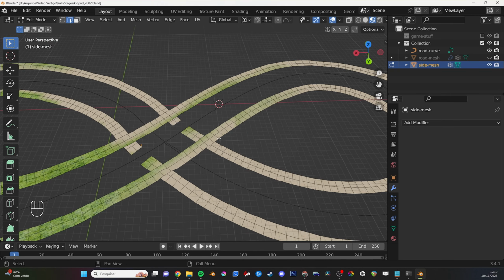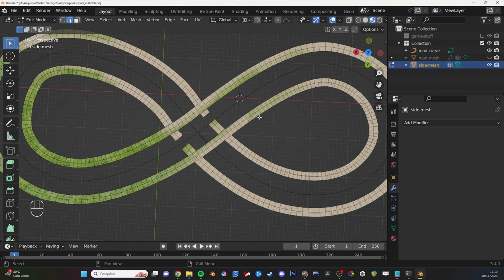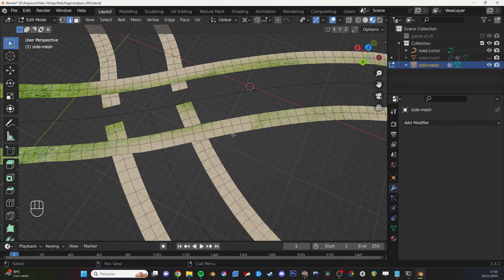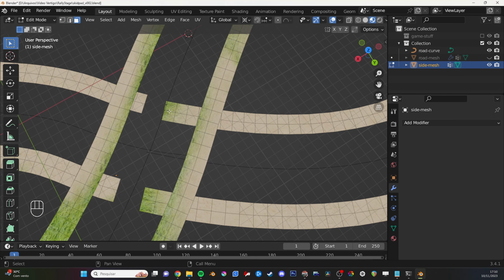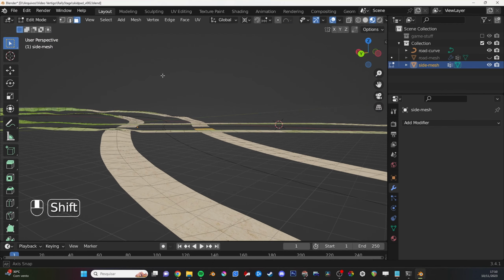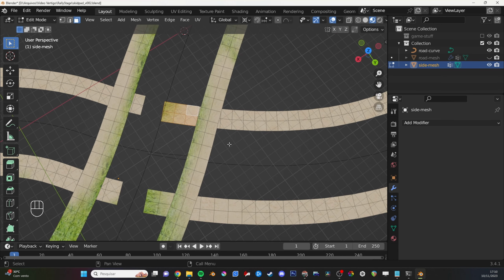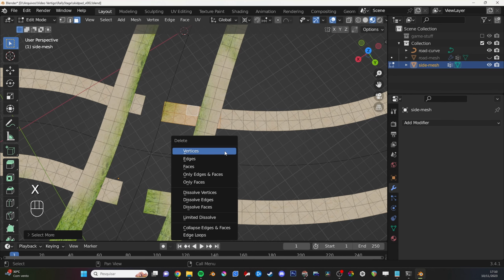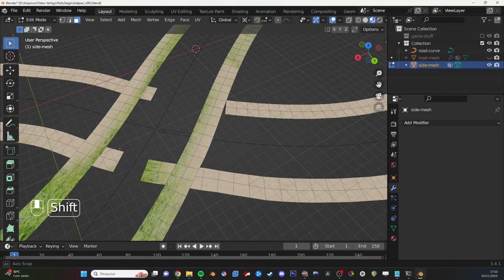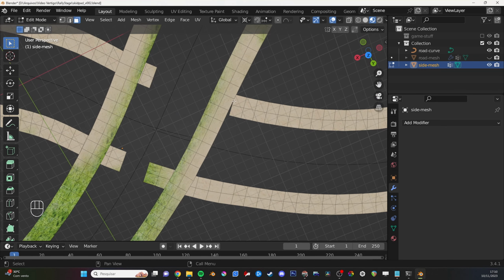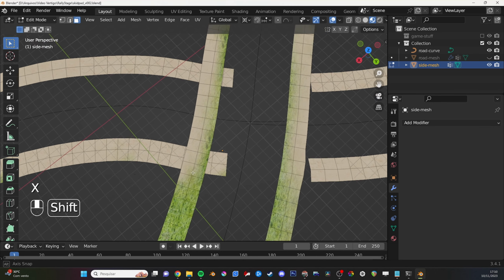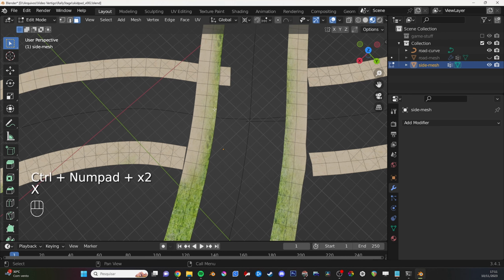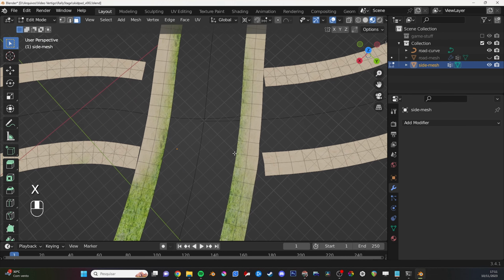So first of all, since we have this complex iteration here on the surface, I'm gonna start with it, and I'm gonna actually delete some of the vertices here, some of the faces. I'm gonna again select some faces, and since they are hidden there, I'm gonna again use the Ctrl plus menu, X, delete faces, leave them like they were just about to touch each other. The same here, Ctrl plus, delete the faces, here the same faces, and here the same, delete the faces.